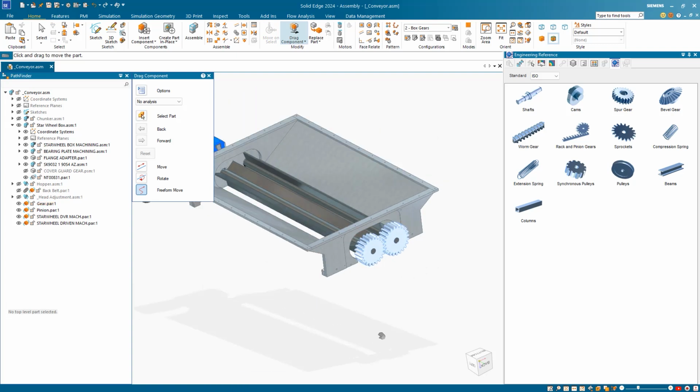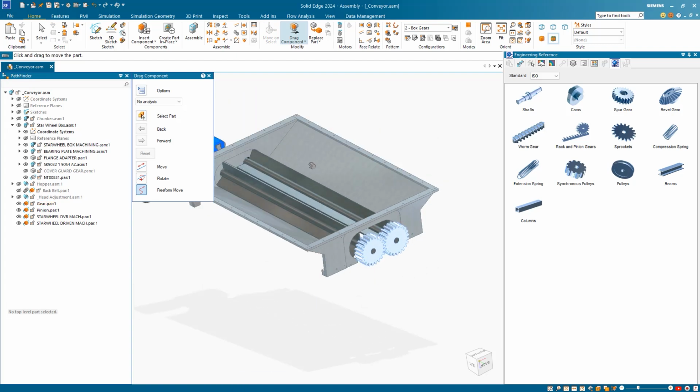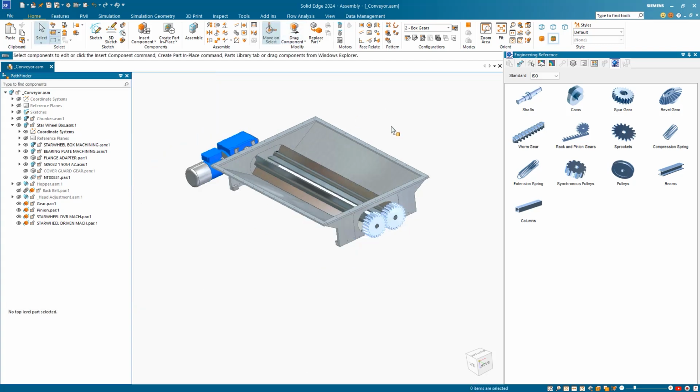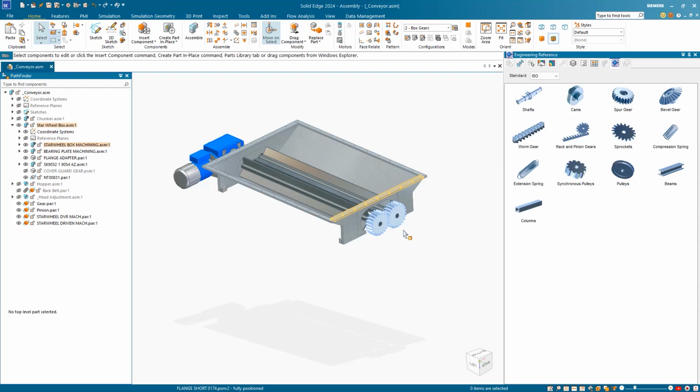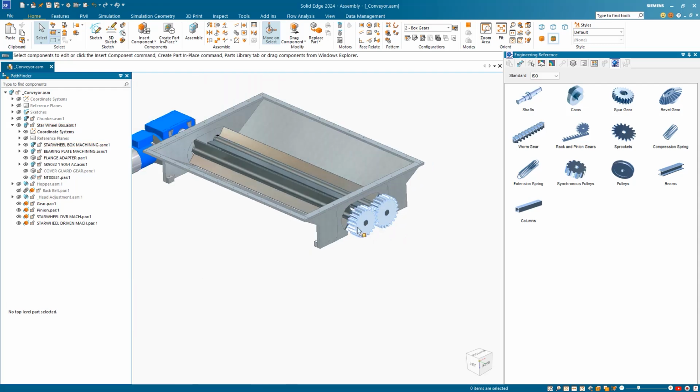This is exactly what we wanted. So when I'm trying to move the gear, the shafts move along with that, which looks good. Now, one more thing that you can do is assign a speed to this gear. And that can be done using this rotational motor option.